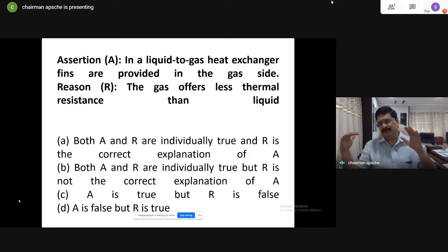I was explaining to you about the boundary layers formed between two adjacent fins, and the gap should be sufficiently long. When you are using liquids, the boundary layer thickness is very high. Therefore, when you use liquids as a convection medium, the gap between the fins should be very large, so that fluids can very easily flow between the fins and come out.